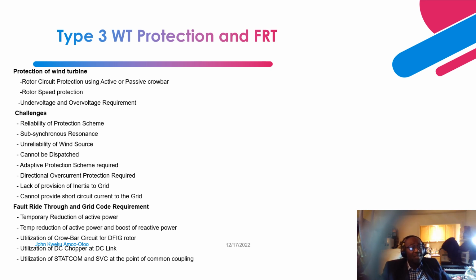Then you can also boost your reactive power, through your power electronic controls, or through installed reactive components such as capacitors, or static compensators, or STATCOM, static synchronous compensators.